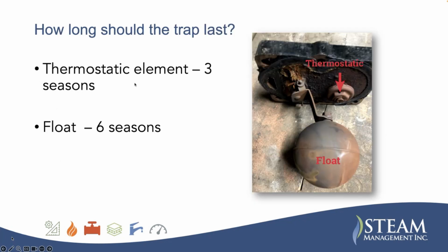So most of the experts say the thermostatic element, which is here, this is what allows the air out, lasts about 3 seasons, and the float lasts about 6 years.